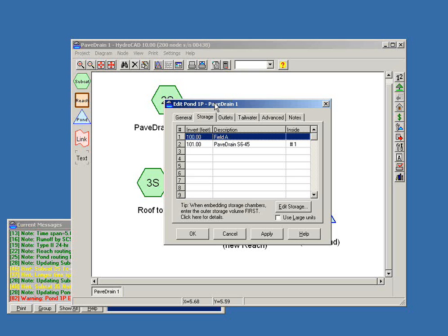Right. We just did an ASTM pervious test on the system, and as hard as this may be to believe, they were looking for a minimum of 8 inches per hour rain event, and the calculations showed the Pavedrain system could handle over 1,000 inches of rain in an hour. That's how fast it infiltrates. In terms of a rate, it's just staggering. And we have video of it.